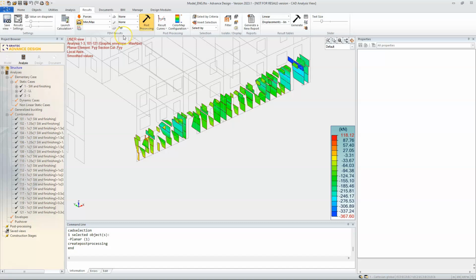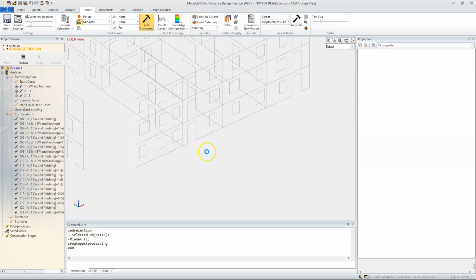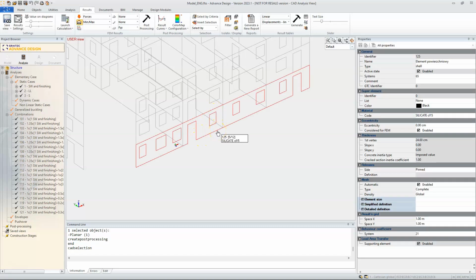So the internal forces right now are the basis of our design. But as I said, the design forces that we will finally use are calculated using the strip method. At this moment, we can see what will be done because we need to provide some strips. But what's most important is that automatically, by default, the strips are assumed between the openings. So each panel between openings will be calculated on this integrated effort.